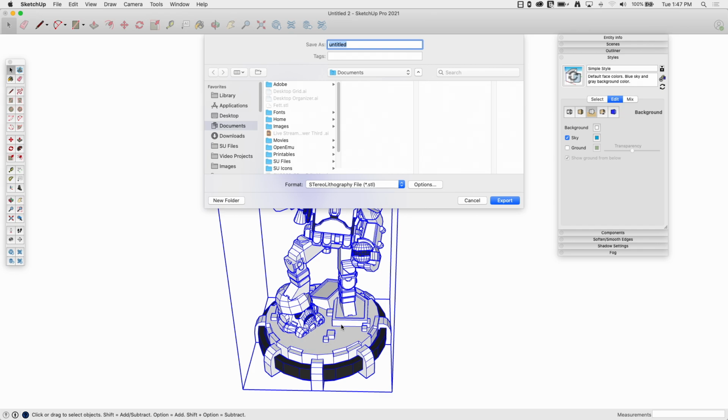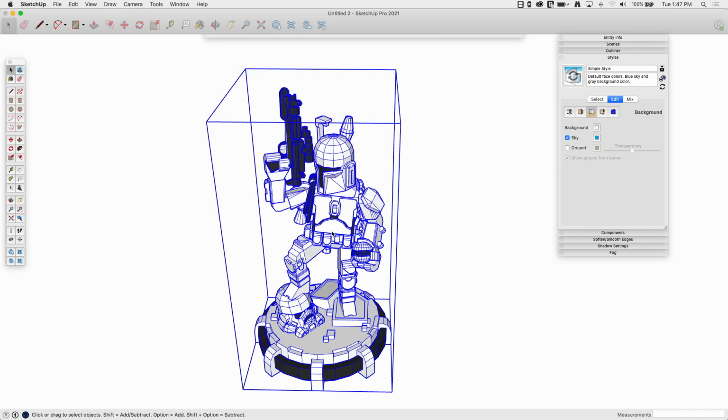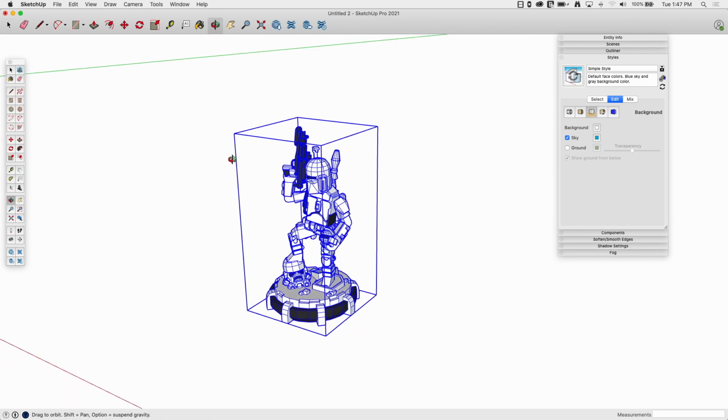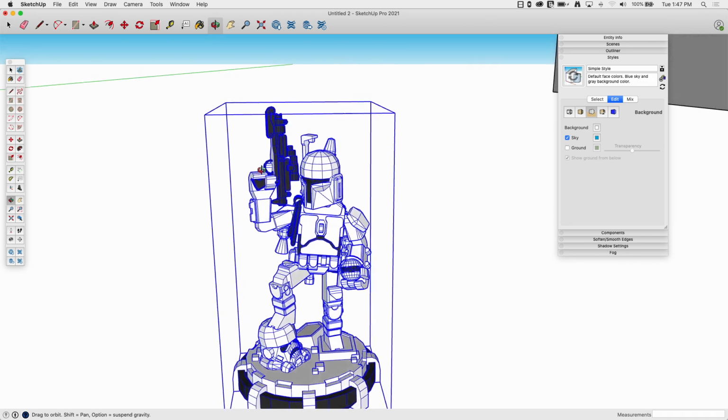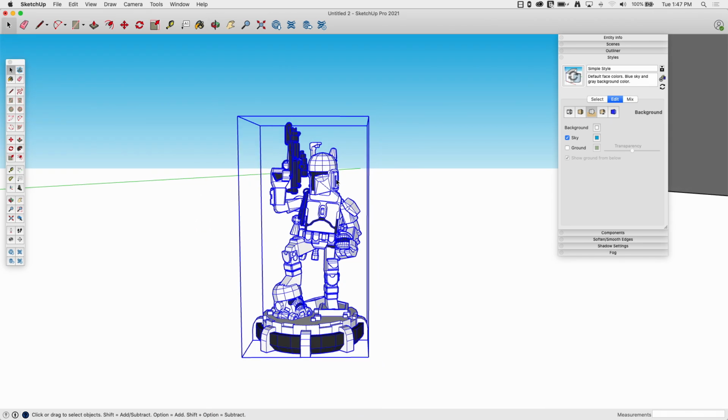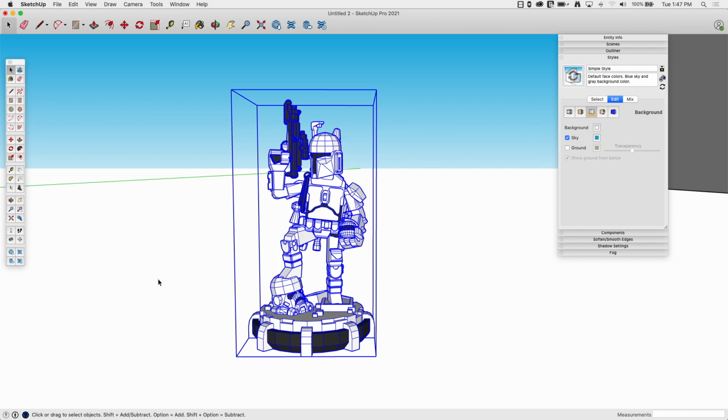A lot of people use SketchUp alongside things like 3D printing or creating assets for animation. SketchUp itself doesn't do a lot of that work. That's all done by creating the geometry in SketchUp and then exporting it to other programs, and this is how you do it. This would always be coming out of SketchUp. 3D models want to go out, they go out of SketchUp. You would not take a model into LayOut and then try to export it for 3D.